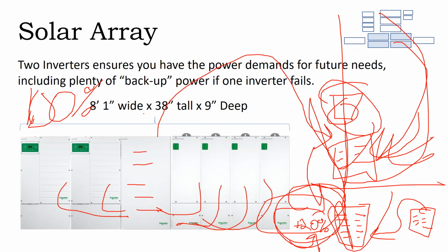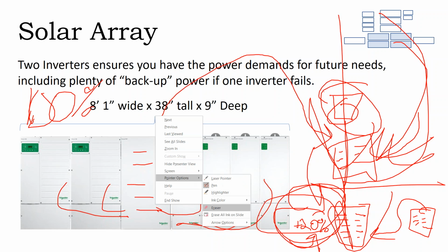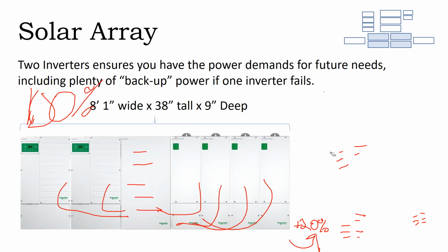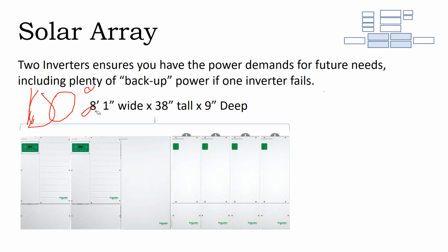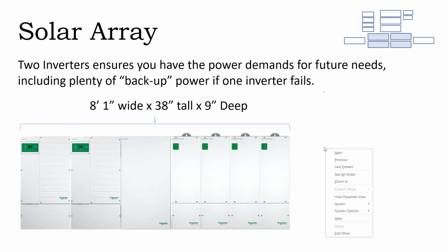A solar array sized to be 20% the size of your electric feeder may be enough to offset 100% of your electric bill. A solar array is on for about a third of the day at full power. Your house is only on about a third of the day and nowhere close to full power. So it's very common that by the breakers, you have a 200 amp service and a 40 amp solar array. It's very common for that 40 amp solar array to net out the bill.